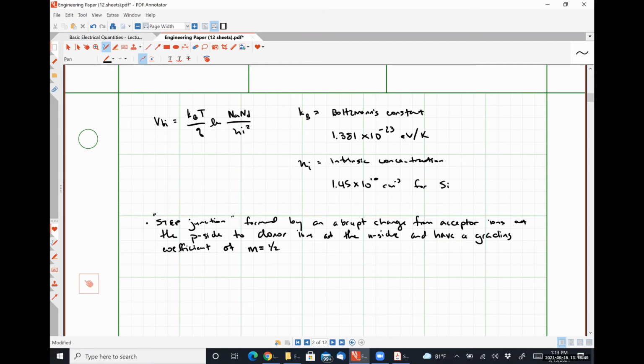If you look at the equations I gave you for junction capacitance as a function of the unbiased junction capacitance, in your 335 or 336 notes, that equation probably looks super familiar, but all that stuff on the bottom was underneath the square root. It's because the textbook we used said all junctions were step junctions, which is not remotely true.